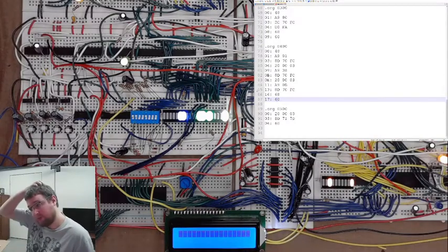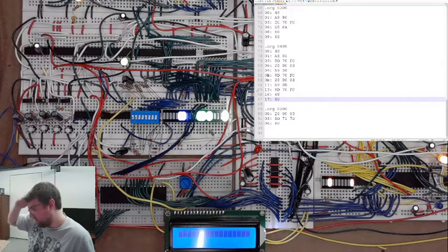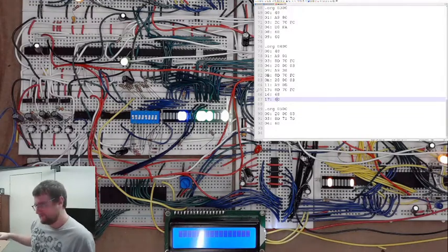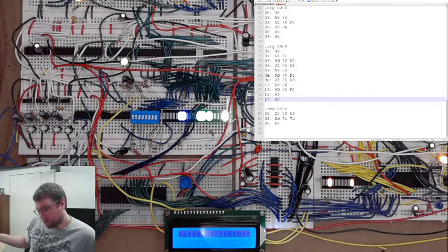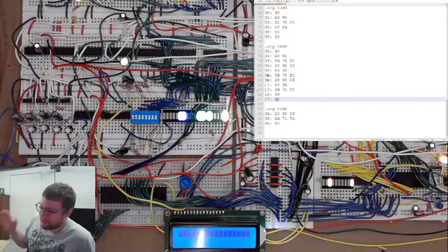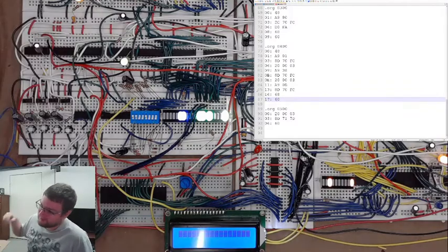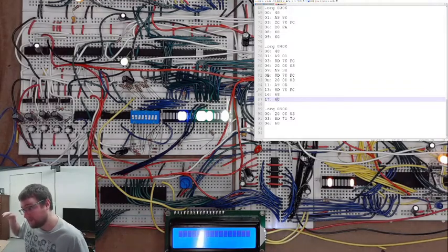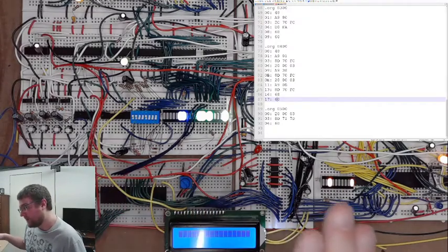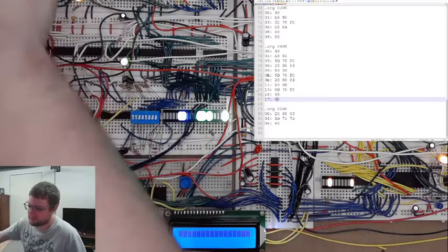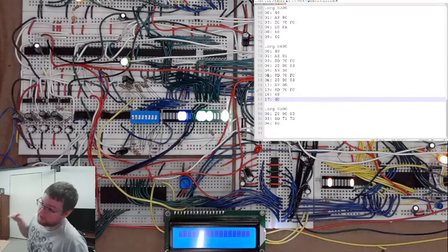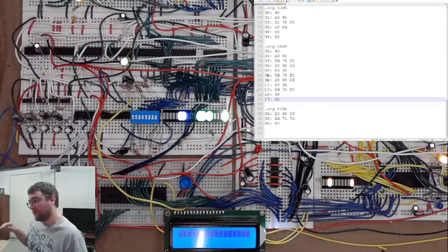And because SPI EEPROM is such a simple thing, we don't have to have a file system or anything to do that. And we get a lot of RAM. Then the EEPROM, if we want to, we can boot from a file, because the EEPROM can have a file system thing. It can have an SD card driver, and it doesn't have to have a file system. We can just have it have a very specific sector that it looks for to boot, and it can boot from that sector, and we'll call it good.